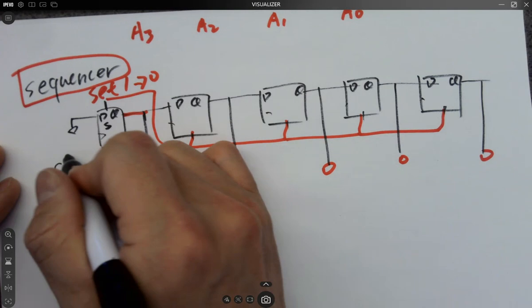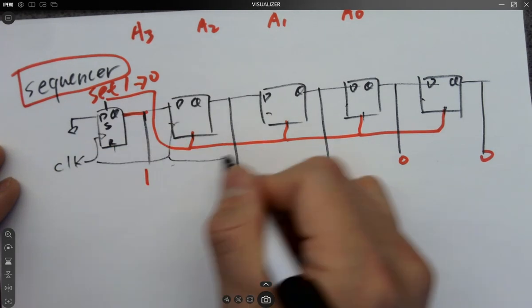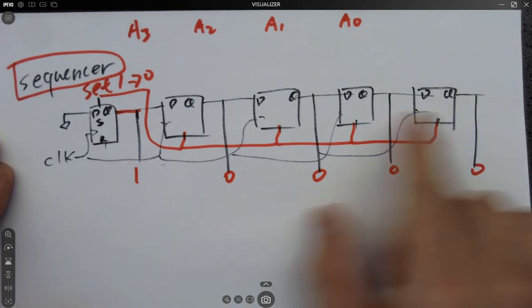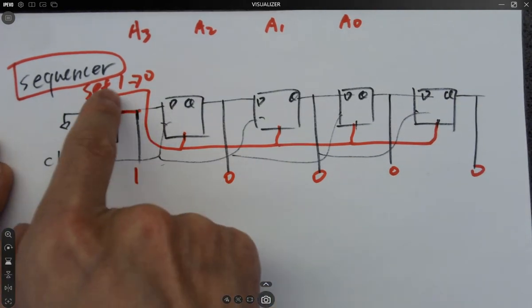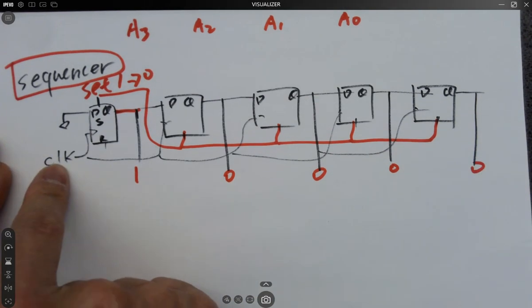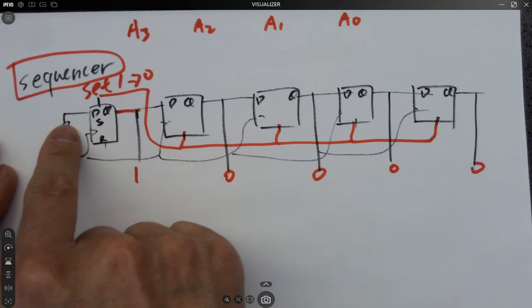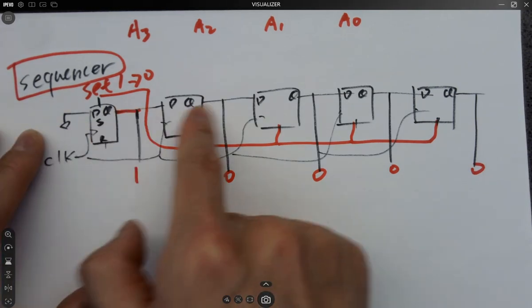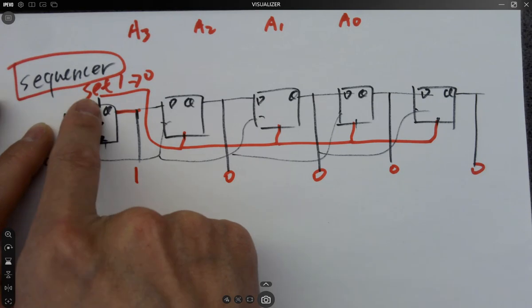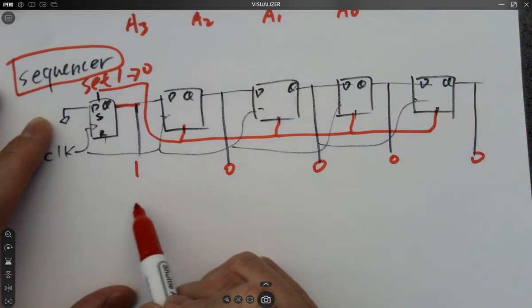So these are all synchronized clocks. They happen at the same time. It's a shift register. So after the first cycle of set and reset, you use the normal clock. It's going to keep pumping zeros to the right because you short the first D to 0. So eventually you are plugging zeros in front of it.